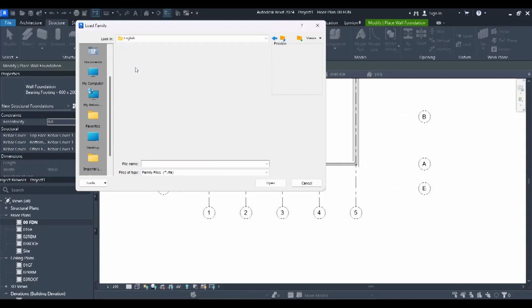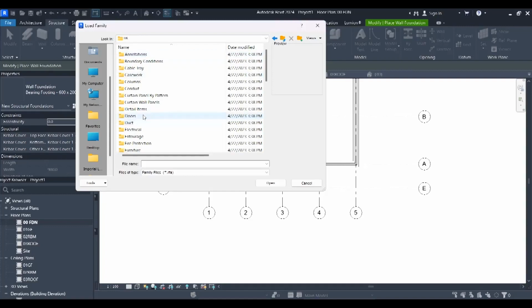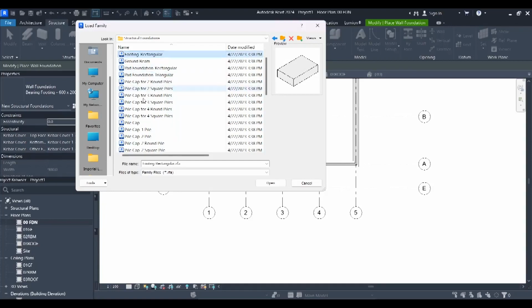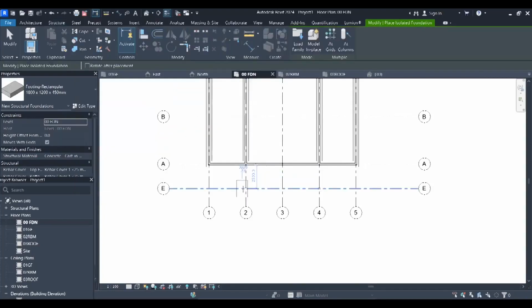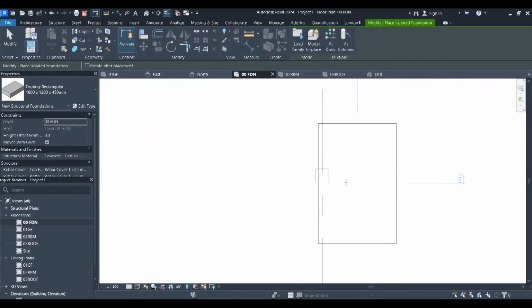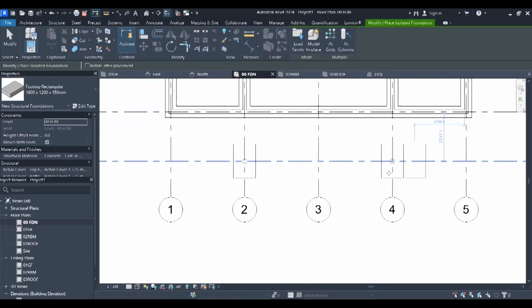So let me use English and use UK. I can even choose US as it had brought to me. Then I go to foundation, structure of foundations. Then you can select one. Footing. This is a pad footing, rectangular. You choose that. Then now you can place it. You can change it also.